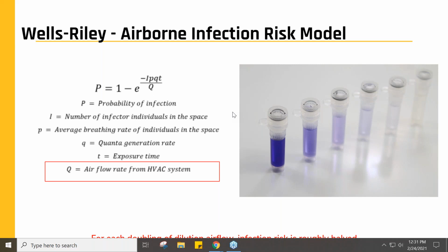So Christian Tabor is also on the line. Christian, anything you want to add there? Well, I think fundamentally the real question is where the disinfection or the dilution of pathogens is being done. If you're comparing HEPA filtration to in-unit ionization, the goal there is the same. What you're trying to do is remove any concentration of pathogens from the HVAC system.